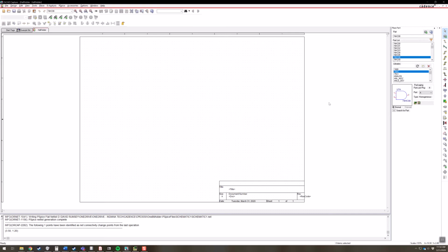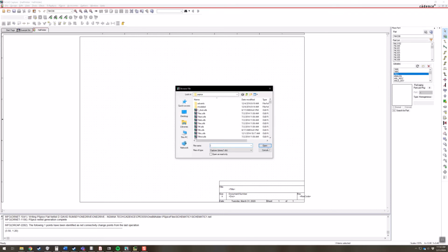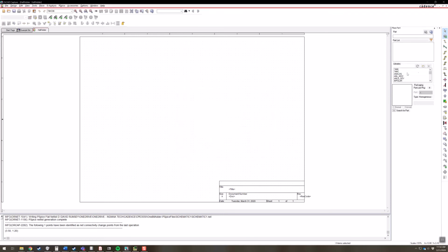And then what I'm going to do is draw the circuit for a half adder in here. Now, I have been playing around with some of these libraries for the TTL logic, and some of them don't have their digital simulating properly. I found that the 74HC library is really the one we want to use.